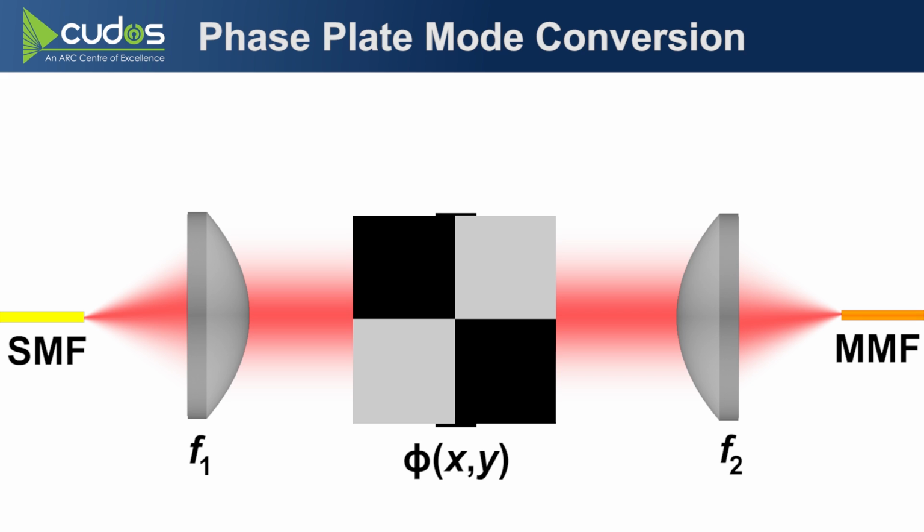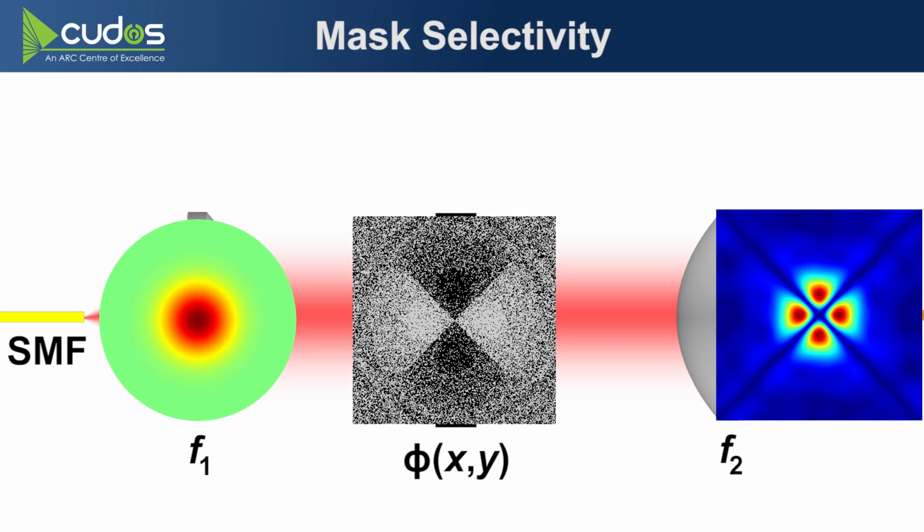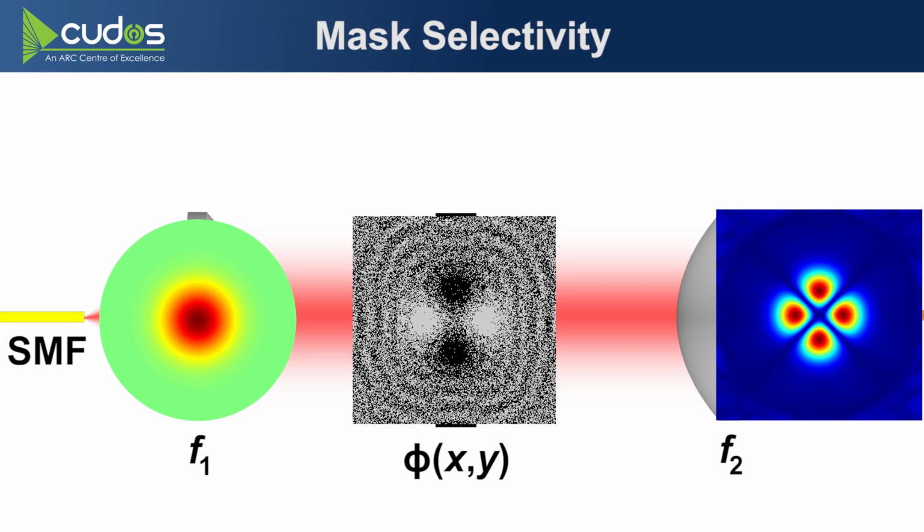When you make these simplified masks, information about the phase of the mode was kept to make the mask, and the amplitude information was simply discarded. So in order to get that information back, you need to generate phase masks which take the amplitude distribution of the mode into account. I talked about that last year, so I'm not going to go into details, but you can look up my talk from last year on YouTube. My point is, when you start characterizing systems or components that support more than about 6 modes, having more accurate masks becomes important.